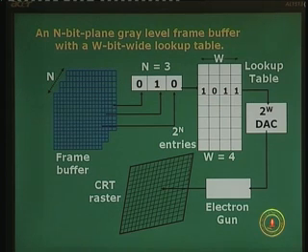In fact, increase W, take W equal to 8. If you take W equal to 8, what are you visualizing? Well, the size of the lookup table in terms of its entries could still be 8, that depends on the value n, which is 3, but you can now choose those 8 colors from 256 colors, because W is 8 bit wide. So, there are 256 possible color values or gray level intensities, and you can choose just 8 out of 256 and load the lookup table and address just the corresponding 8, and you will then use a 2 to the power W DAC, because the output will be W bit wide from the lookup table.